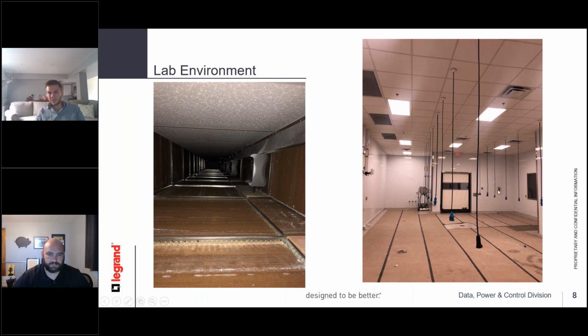One of the things we did for this particular end user, which we don't normally do, was the plug-in unit separate from the cords. We don't typically do the cord sets separately, but in this situation, the customer said, if you wire these off and I buy these plug-in units the same way as normal, once they hit the site, I have to open up your plug-in unit, unwire the load side of the breaker, remove this drop cord from there, slide it up through this grommet, and then try to reconnect back into it. And they're like, well, we don't necessarily want to do that.